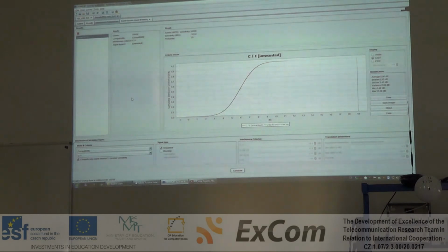Here in SEAMCAT we can do this very easily by changing now. Here you can change from compatibility to translation. Okay, it is done. Now you have to come here. You have a window called translation parameters. You select on this upper button interfering transmitted power. Click on it to select it. And here we will define the range of the interfering transmitted power. Right now it's between 0 and 100 dBm.